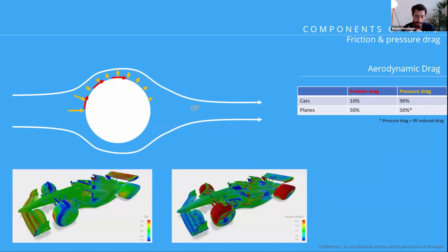When we talk about aerodynamic forces, we can typically split those into friction drag and pressure drag. If you integrate the force of the air on the surface caused by the air sliding parallel to the surface, this is your friction drag, which for low speed applications like cars is usually just around maybe 5 to 20% of total drag. And the majority of the drag is coming from the pressure drag, which is when you integrate the force of the air pushing and pulling perpendicularly to the face.